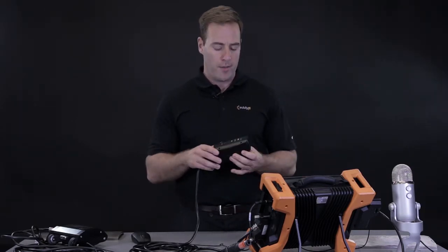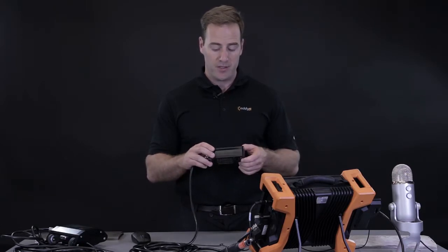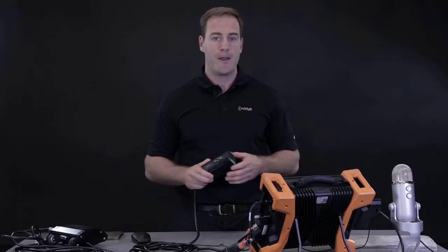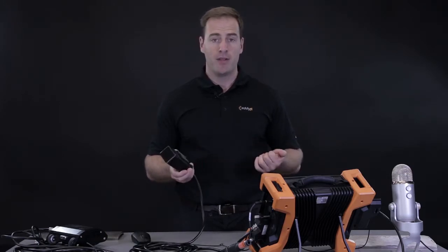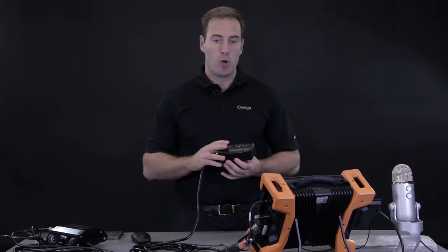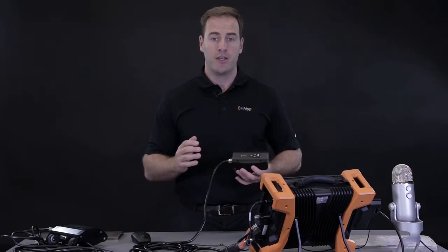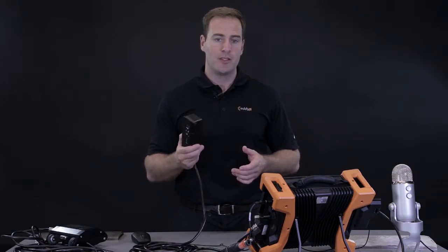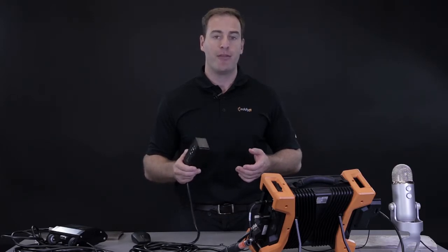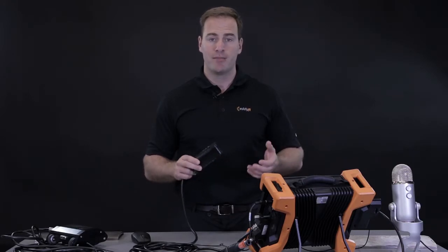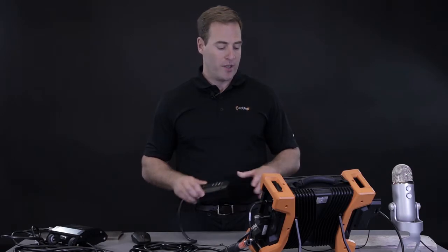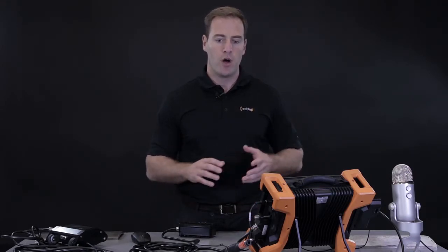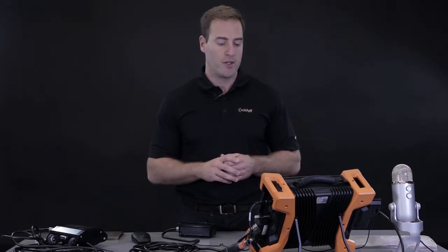Just a few details about the first probe that we're going to use. This probe is able to deal with up to 3 mm of lift-off or coating. So no need to remove the coating before the inspection. Regarding the probe capability in terms of detection and depth sizing, this probe is going to detect the defect or the crack in all orientations, both axial and transverse. And regarding the depth sizing, we're going to be able to size with this probe defects as deep as 7 mm with pretty good accuracy, ±10–15%. Considering the fact that we have to manage the weld roughness, the material properties and many other parameters, on carbon steel like that, this is a pretty high level of accuracy.